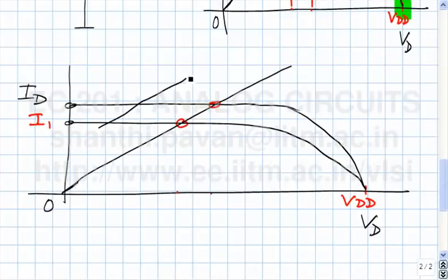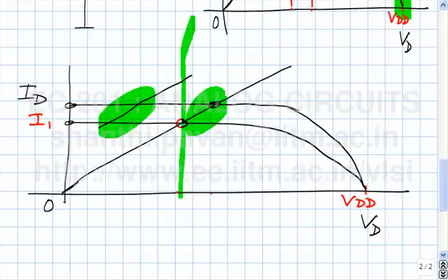To get the same gain, the slope of the resistor must be the same, but must cross much earlier than where it's crossing now. Does it make sense? If the characteristic of your resistor was like this, then you'd be able to use only a small VDD and still get the gain. But now, can this be a straight line?